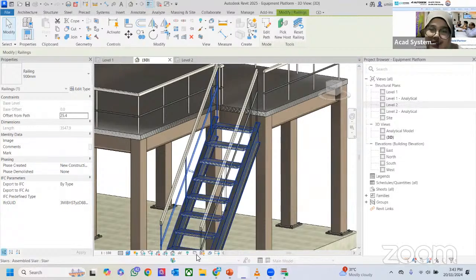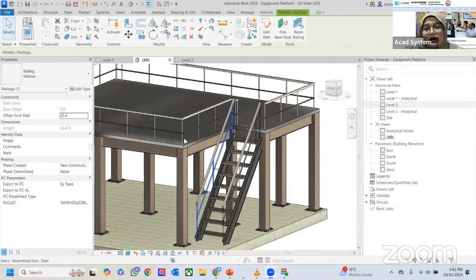Sometimes handrail outside. Yeah. So cannot add handrail just like a hanging handrail. So each railing needs to have a host, either on the floor, on the support like that, or the step. All right. Thank you to you too for the question. So very, very good question actually.